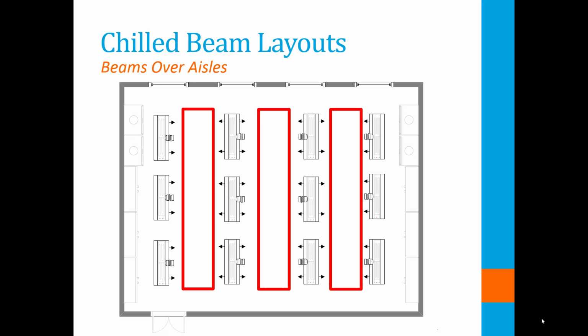Positioning the chill beams in the ceiling grid can be challenging when coordinating the design with all other services that a lab requires, but generally the chill beams are located either over the aisles or over the benches. This layout shows aisle positioning and may be chosen when the ceiling directly above the benches is congested with services such as pipes, task lighting and electrical conduits. It's also easier to access the chill beam cores for cleaning when located above the aisles.